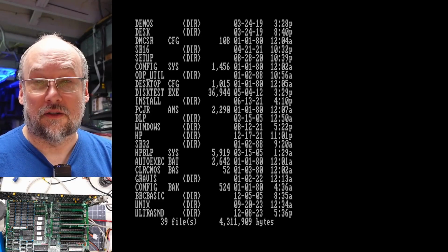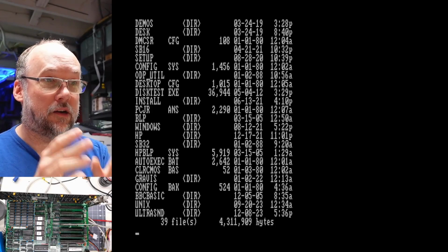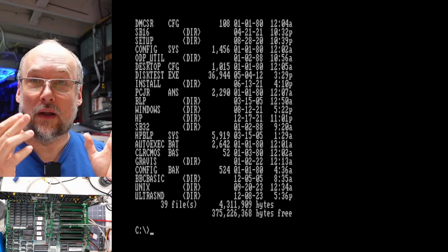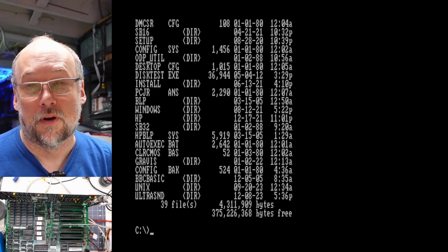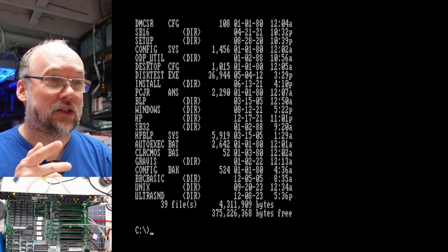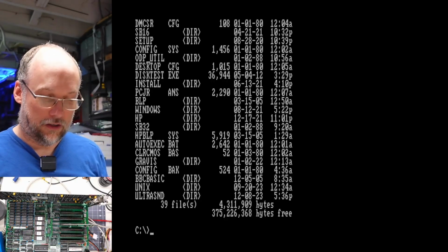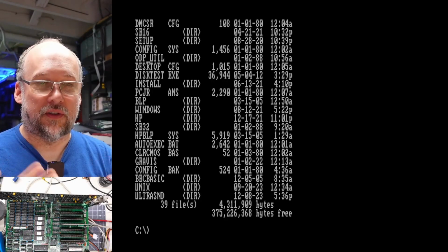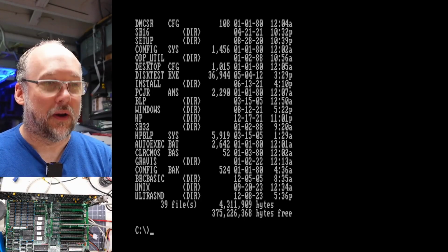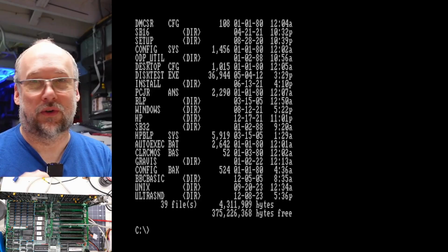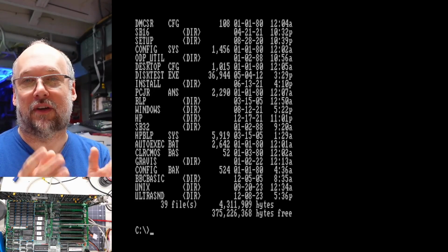The ANSI.sys driver that I'm using is patching those software interrupts that print characters or do scrolling to eliminate that wait cycle, which actually speeds up the text output with the effect of creating snow only on these old original CGA cards. There are other more sophisticated strategies for updating the video memory in a much faster way, but also waiting for the vertical or horizontal refresh to happen to eliminate snow, but also get much faster video update rates.